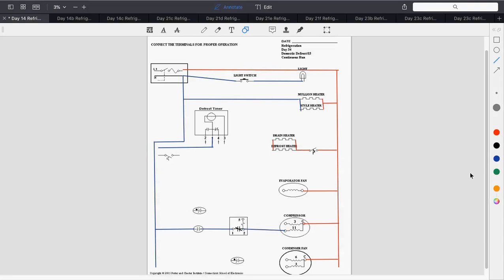Where does pin 5 go? To the run winding. The common. You see this little other capacitor relay goes to coil 3 in there? That picks up the back EMF. That's the generated voltage by that start winding.